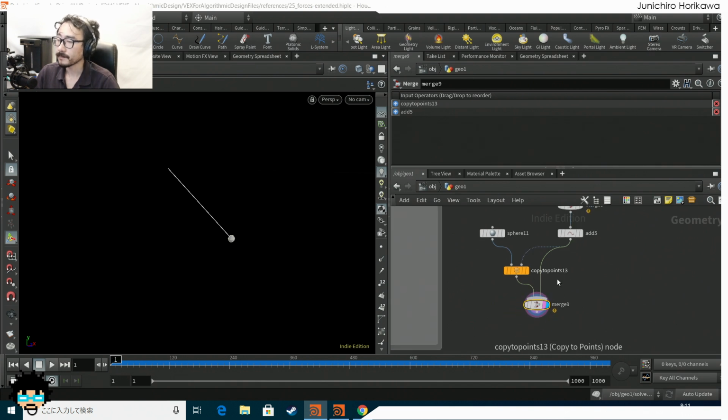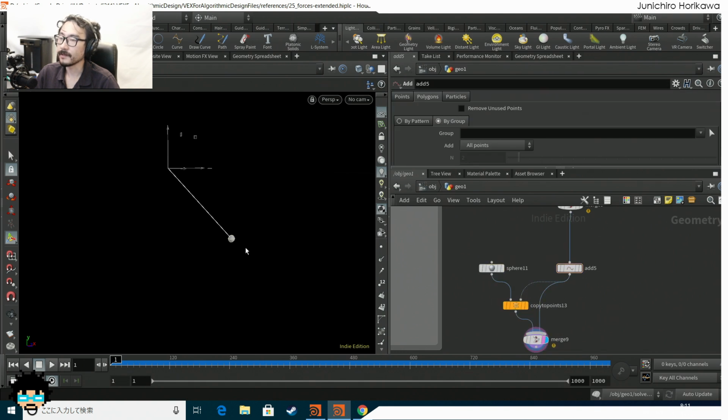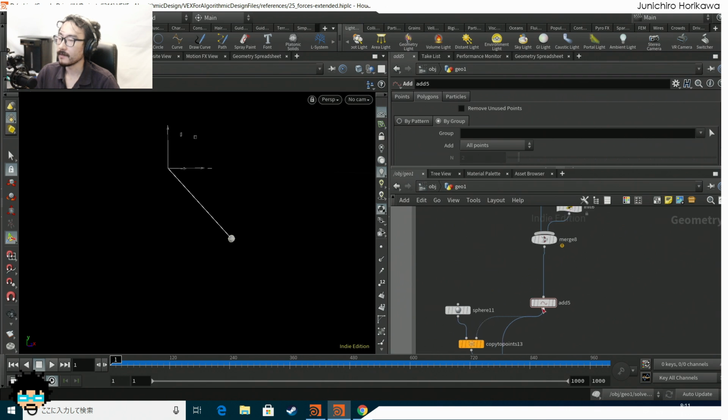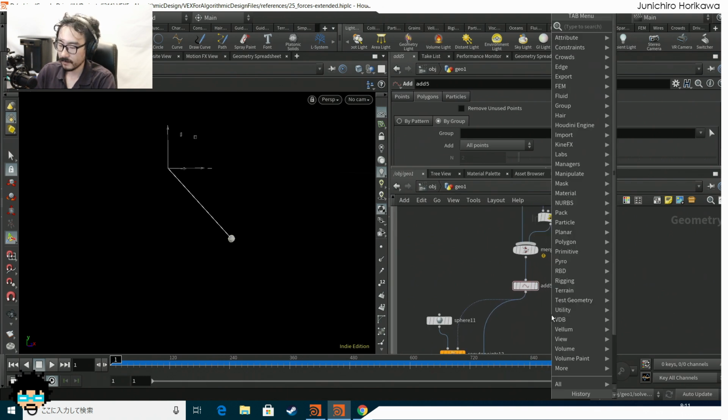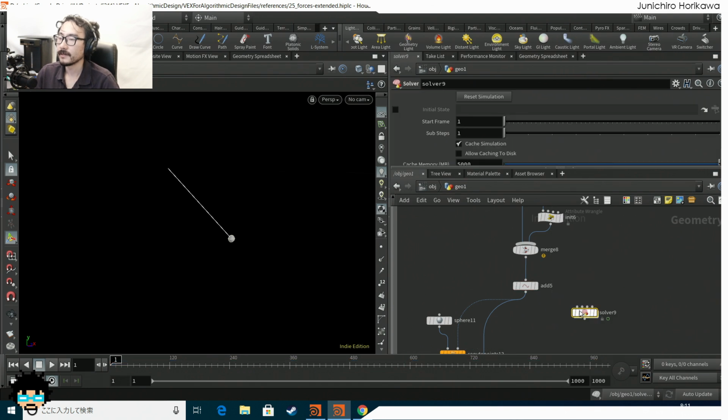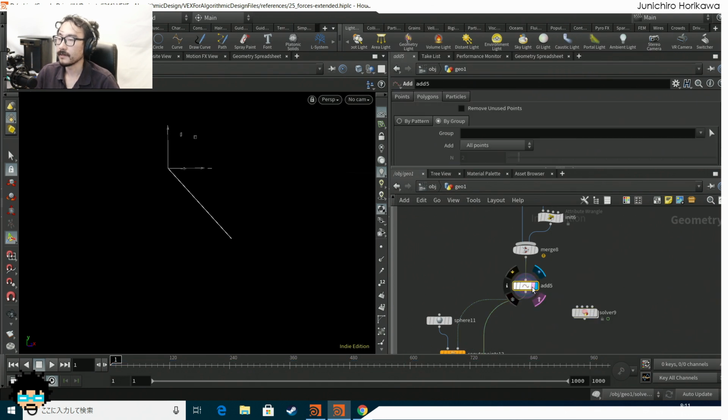Okay, now what I want to do is to move this point using the spring force, moving on top of this line either inward or outward, so that at some point the length between the point and the target, the ball point, will be close to the target length. Okay. So let's do that. I am going to create a solver for this line here.